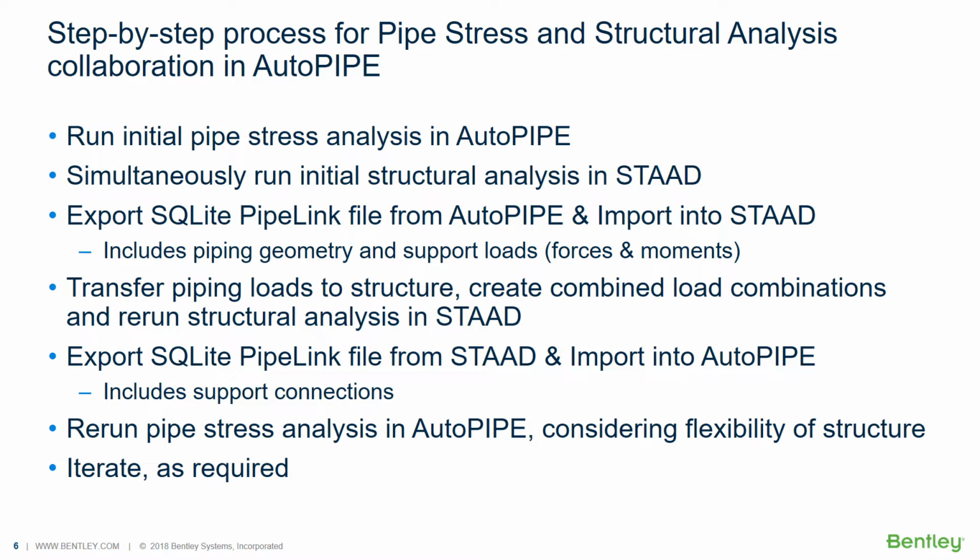Once that is done, the structural engineer can then export the SQLite PipeLink file back from STAAD and import it back into AutoPIPE. And this time, in this direction of the workflow, this export to import includes the support connections. The support connections are going to be made on the STAAD side. So this time it includes the support connections, and on the AutoPIPE side we will automatically see those come in.